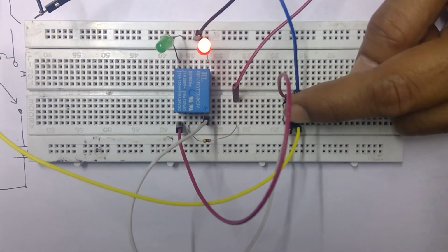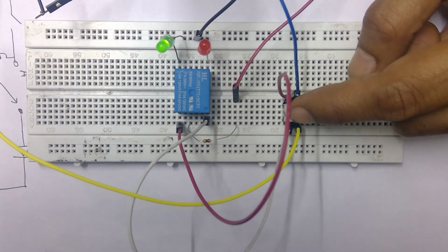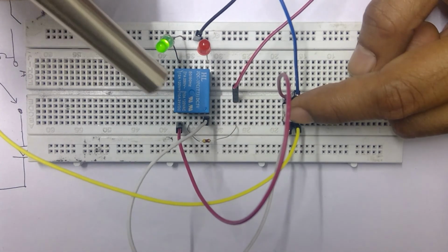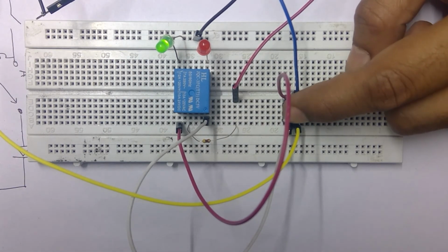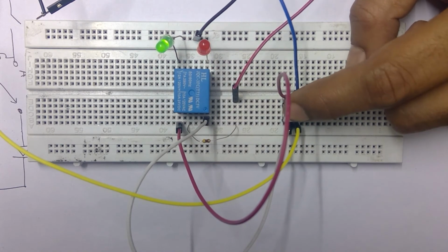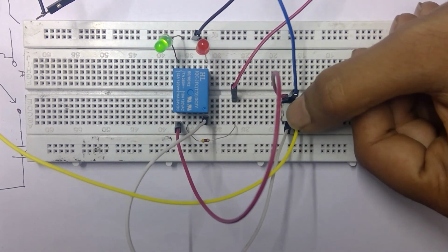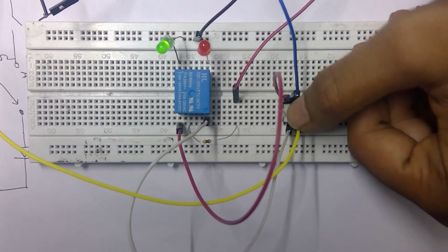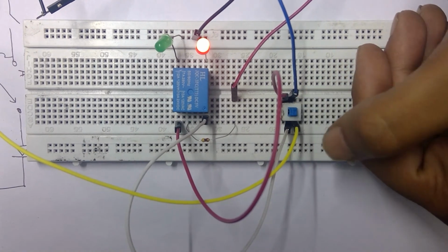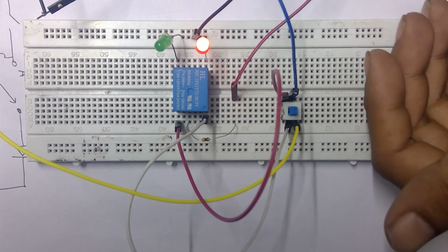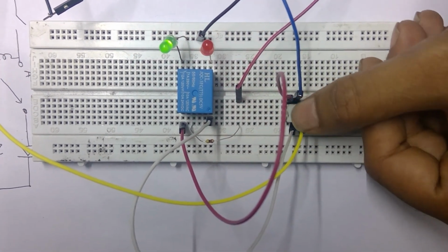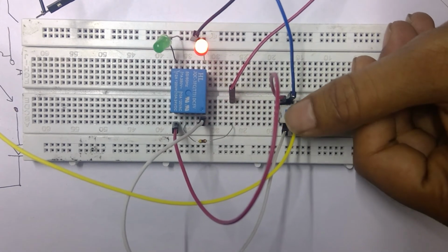Now as soon as I hit the switch, what happened was the common and the normally closed connection broke, and a new connection was created between the common point and the normally open point, and this is how our LEDs are switching. So the switching frequency is also pretty high, although for this example, since we are manually doing it, it doesn't make a lot of difference. But if you want to connect it to an oscillator or any other electronic equipment, the relay can handle a very fast switching speed, which is also one of the reasons that relays are used.